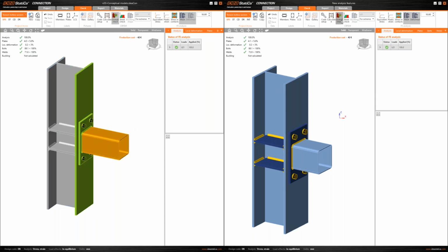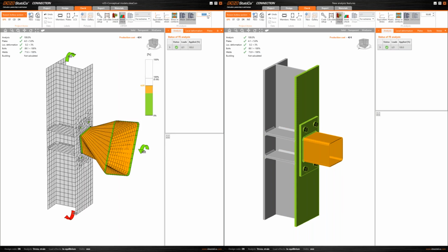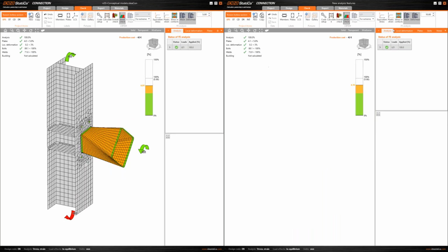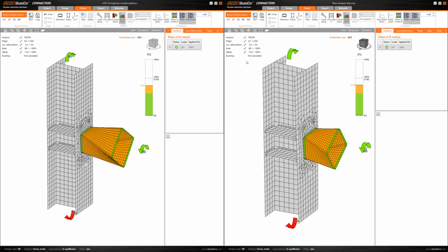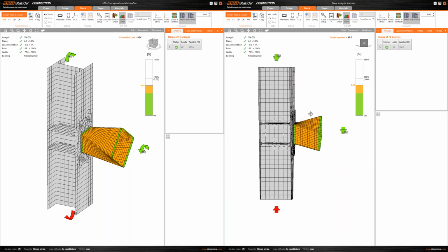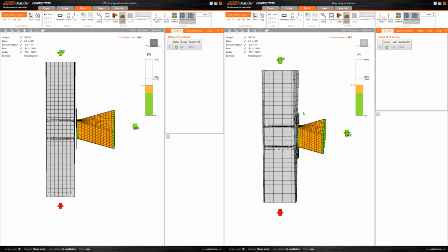windows. So I will activate the overall check, and in the case of a closed cross section that is loaded under torsion, we can see that the results are almost identical. So let me also activate the deformed shape under scale 5. And we can clearly see that we do not have difference in either the solution or the deformations. And the reason is that these closed cross sections are not susceptible to warping. We have a slight difference, which is due to the overall different deformation of the model. As we said before, now the deformations are much more natural due to the condensed super element.